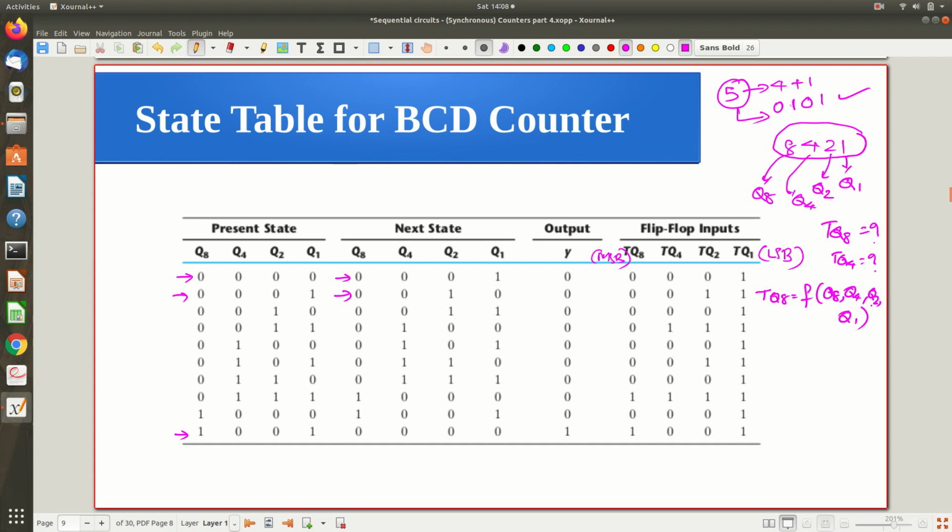Now in a K-map, as there are 10 rows, there will be 16 cells. 8 cells are not enough, right? So now how will you fill the remaining entries? These are all the entries, minterm 0, 1, 2, 3, 4, 5, 6, 7, 8, 9. So minterms 7 and 9 are 1. Now what about minterms 10, 11, 12, 13, 14, 15? You have to continue filling those as don't cares in the K-map, because these are all invalid in our case. If I reach, due to some worst case, something like 1010, that is invalid for me. I want states from 0000 to 1001.